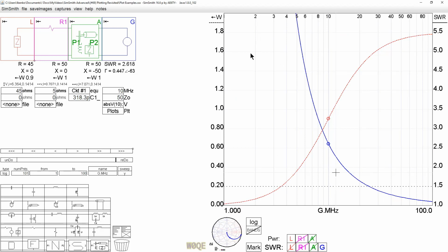And we also have the square chart. The square chart is interesting in that it has four axes, with an extra axis over here and an extra axis over here that aren't shown right now, and they're not available to the user without doing a little bit of programming. But it does provide a power axis on the left, which is controlled right here with whatever we choose to plot, and an SWR axis on the right, and again, we're choosing based on what we choose to plot. The SWR axis shows a solid line under it, solid line in the graph. The power axis shows a dashed line in the graph.